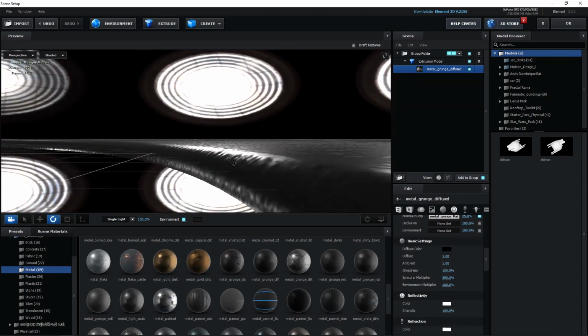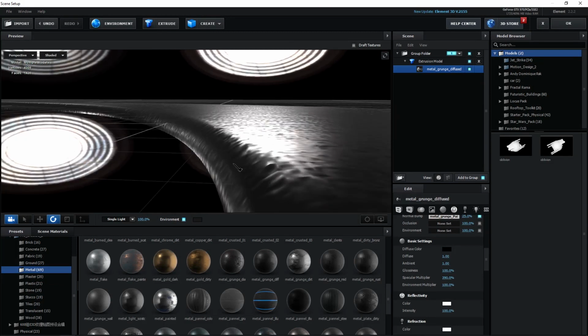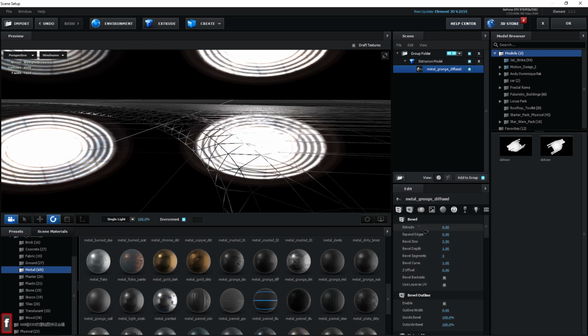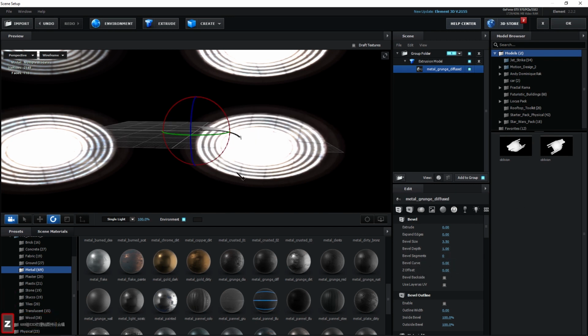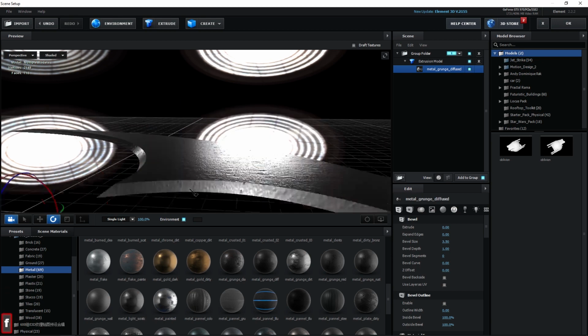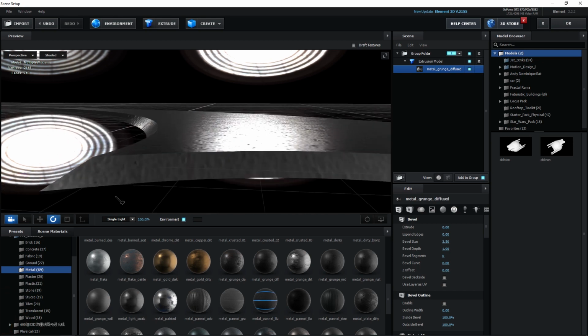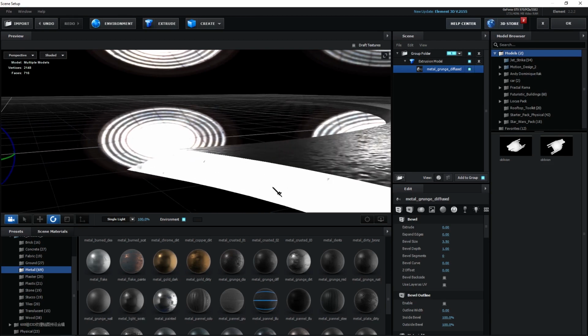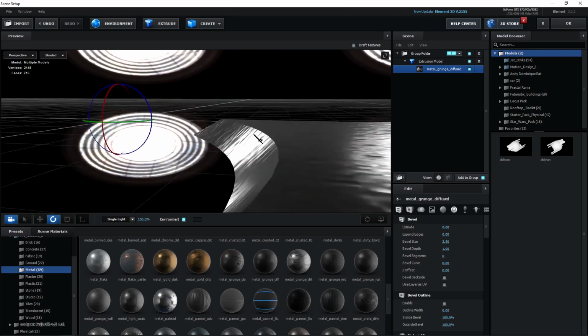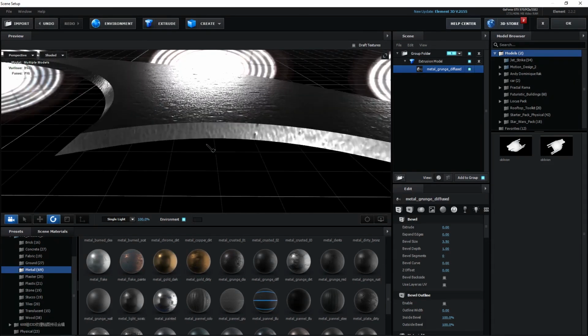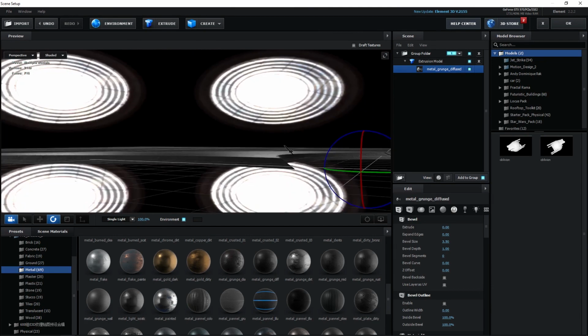And now we can adjust our bevels here and come back to our bevel settings. First of all, we need to adjust this to 0. And now set the bevel curve to 0. So we can get this sort of effect, cutting down this curve on the bevels. Alright. And now we create this sort of effect.